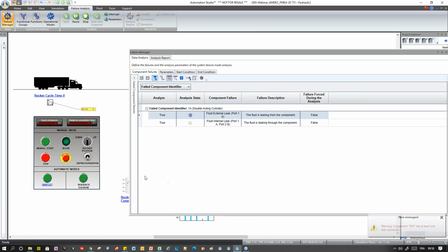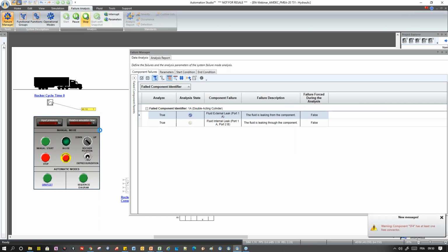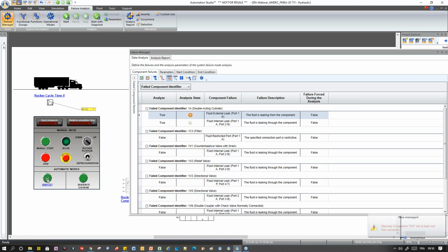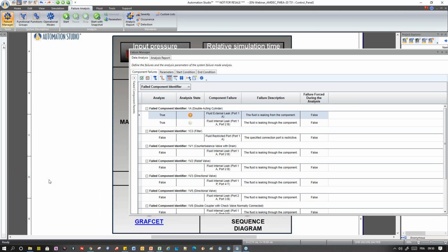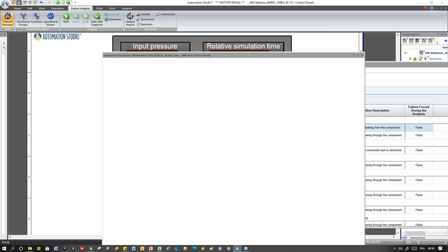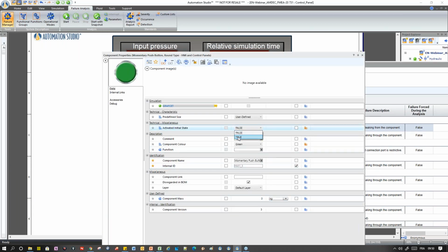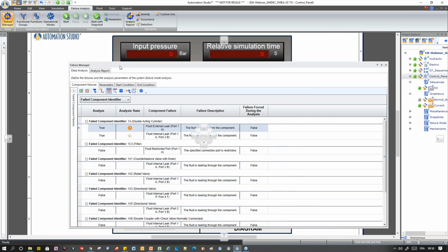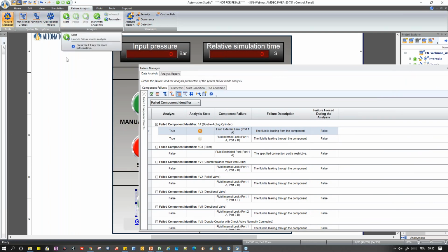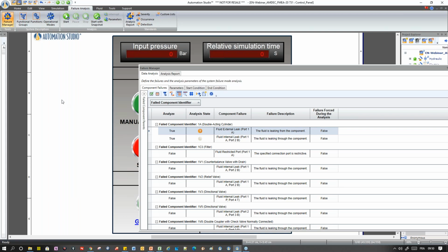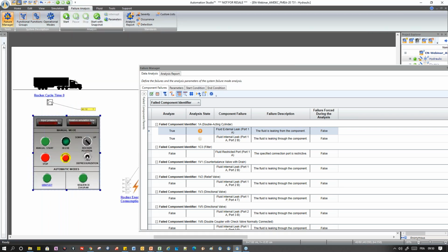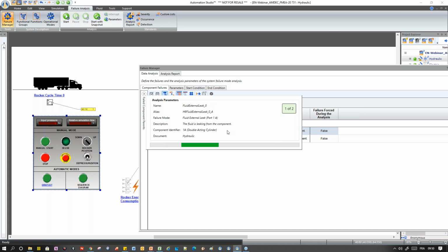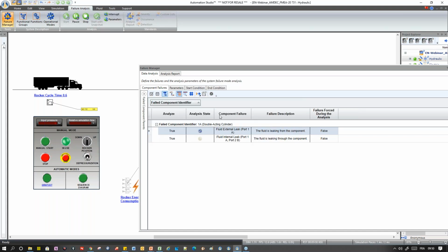I don't want to hit the reset button or the sequence diagram or the manual button. So I have an easy function to force this button to be activated at the beginning of the simulation. If I use the sequence diagram, I can also ask it to start by itself each time at the beginning of the simulation. And when I start now, let me just get back to the main circuit and I will start. So there is the dialog and the sequence will start by itself.